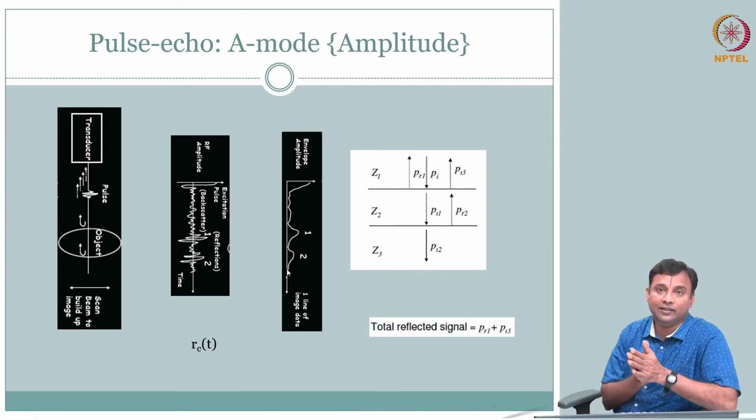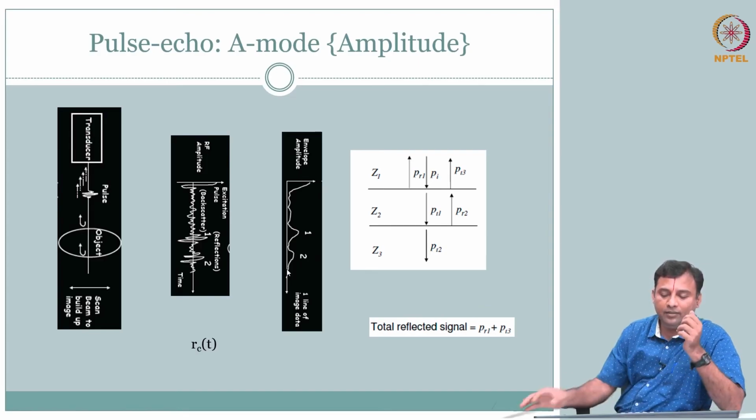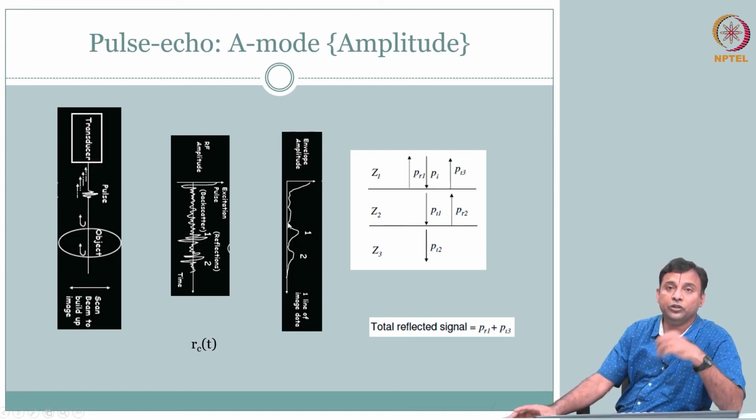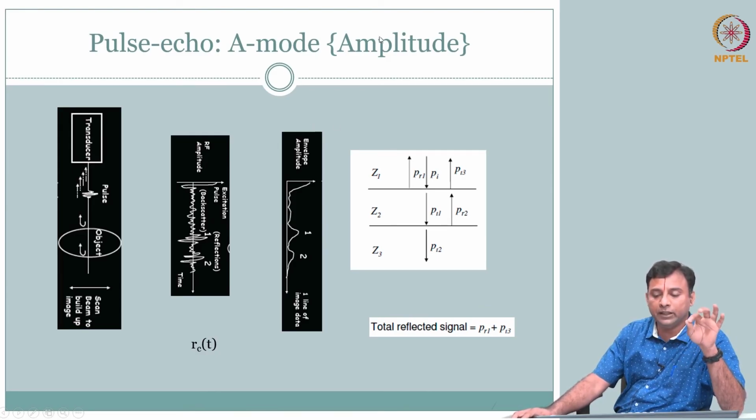Typically in non-destructive evaluation for materials, the same concept is used. If I have layers, and there is a layer where it is delaminated, for example, or some glue is gone, bonding or a crack is there, then only at that location you will get a huge echo. So they have to find out where. Similar thing. So the envelope amplitude signal, A mode, is very useful.